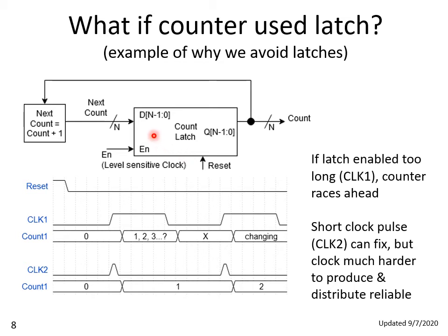And the input to that register would be a block that just increments the value of the count, which is the output of the register. Okay, so far so good. This looks like a counter, except that instead of a flip-flop based register, I've created a register, which I'm calling the count latch here, that uses level sensitive latches. It's possible to create a counter this way, but it is risky. And I'm illustrating below what happens.